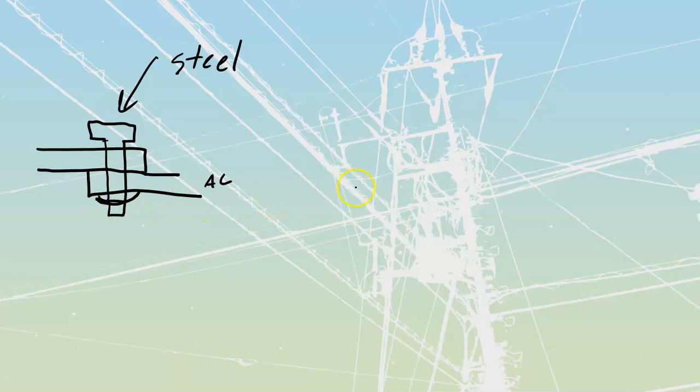That's a washer that is cupped like that, which means that as I tighten down my nut on this side over here to whatever the spec is, this is going to be always a little bit bowed. We never want to flatten them all the way down. If you flatten them all the way down, there's no point in having that conical spring washer, but this thing is going to be pressurized.